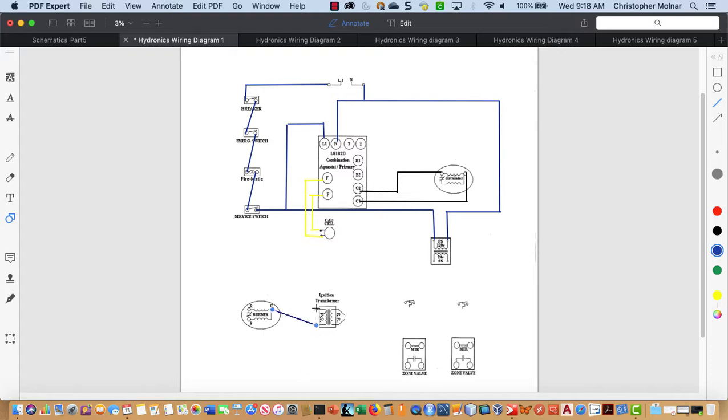I'm going to do that. Now once I connect power to this, we can know that our B1 and our B2 are going to energize those two components at the same time. Be careful you never connect directly to the start winding. You only connect to the run winding.